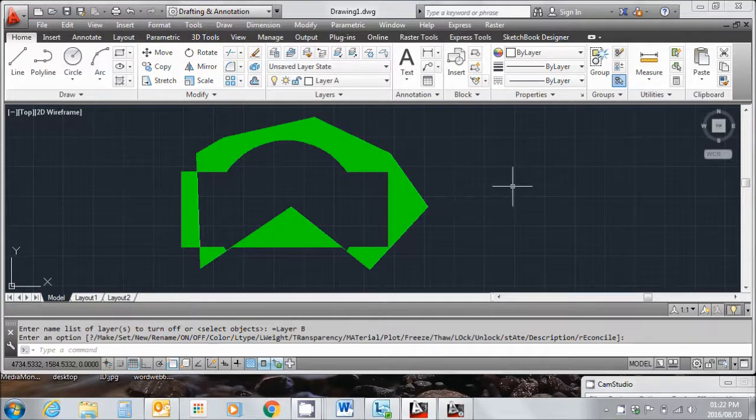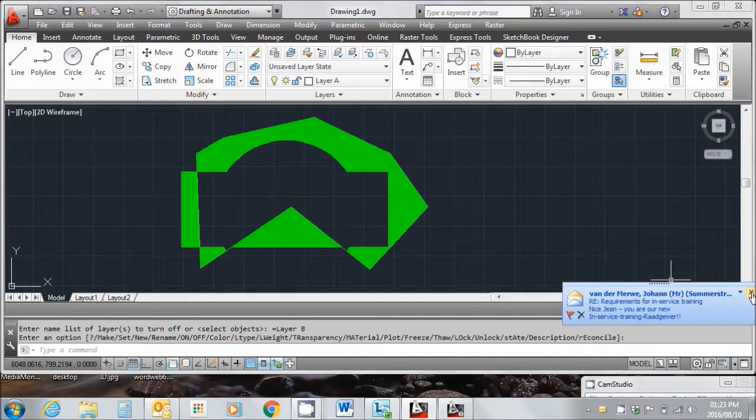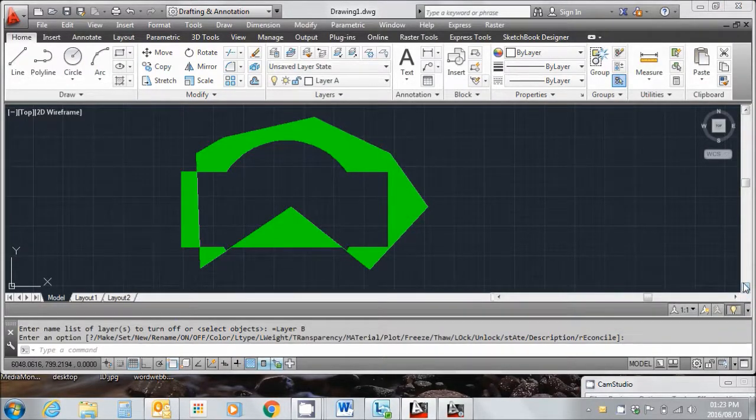Now, in our civil engineering drawings, we do all things that fit together in separate layers. So the S4 project students now are busy doing a service design, which means water, stormwater, roads, and sewer and properties. Each one of those things gets drawn in its own layer. And then once it's drawn in its own layer, then I can import that information into Civil Designer, which will look for things in specific layers.